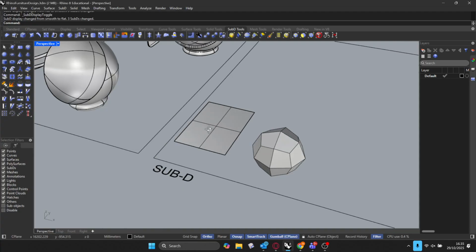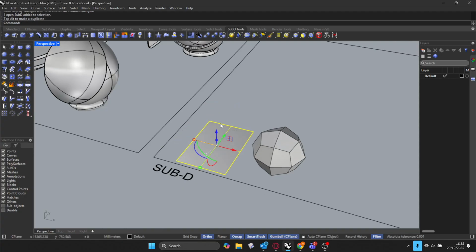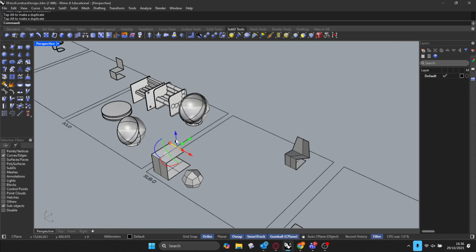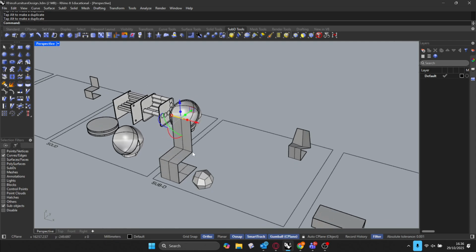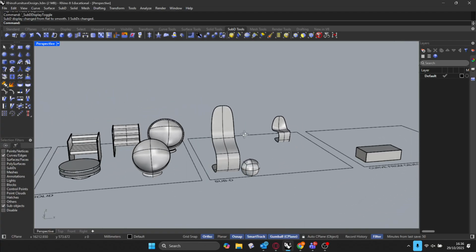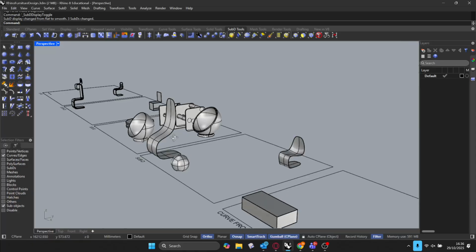And what I'm going to do with this surface here, similar to my other commands that I've done, if I select an edge, and if I hold shift to select the other edge, so using the sub D tools, again, I can hold control, I can start to drag this guy out and I can drag out a shape. But now if I hit tab, you'll see, because I'm using sub D, I get this more curved object, okay?